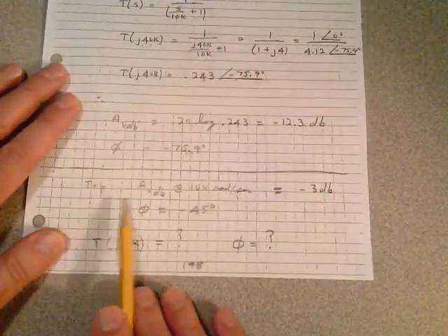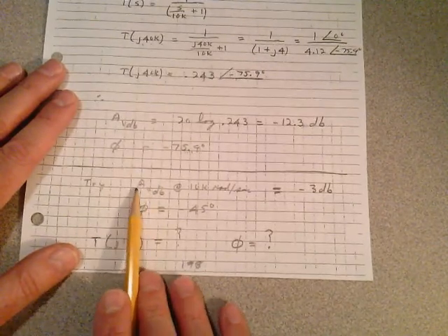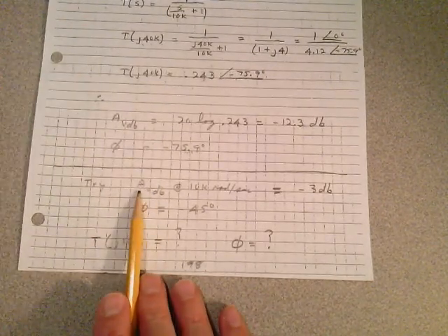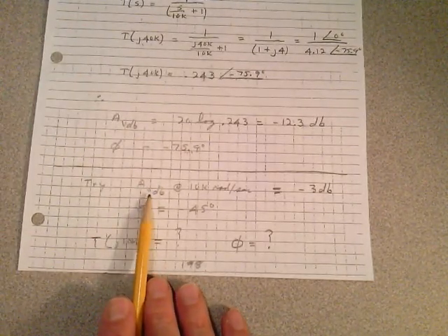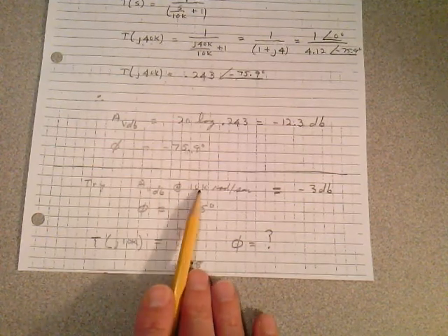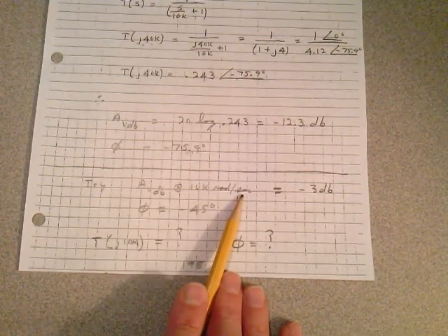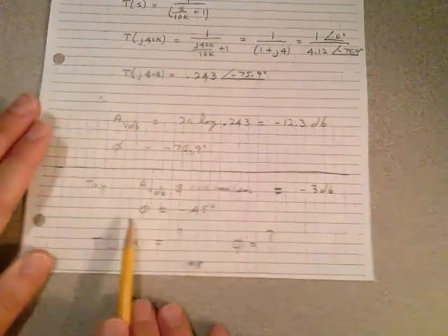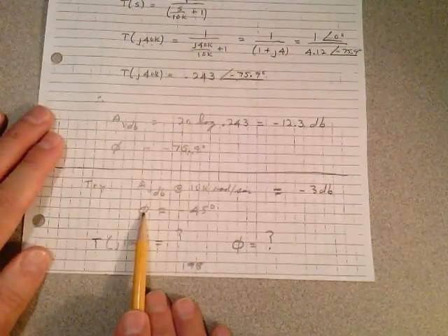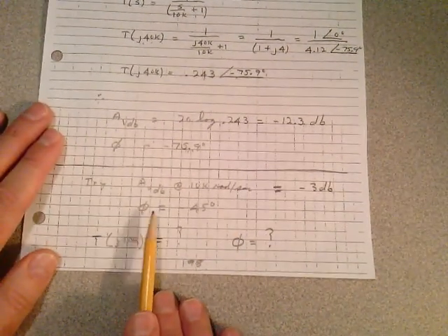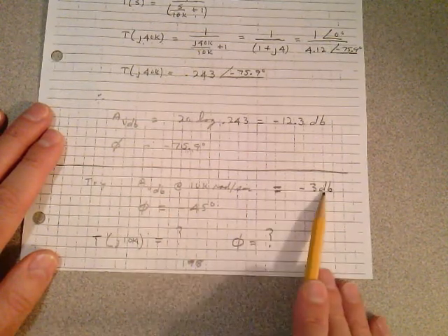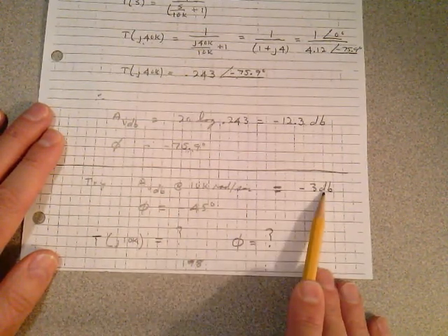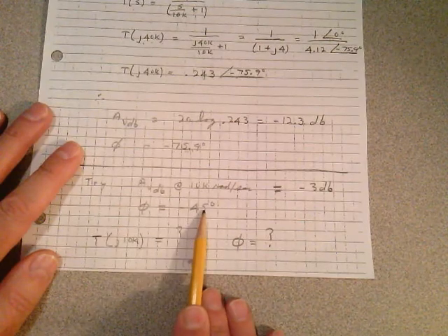I want you to go ahead and try to read off the graph where you would be at voltage gain and dB exactly at the break radian frequency. And look at the graph and the phase and see where you're going to be. You're going to be at minus 3 dB at 10K radians per second. And you're going to be at minus 45.